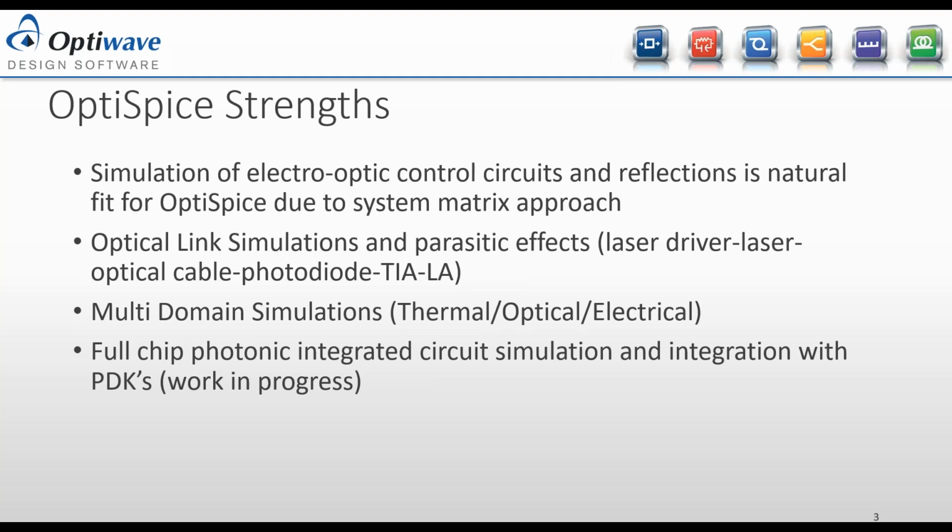One good example would be if you have a laser and near this laser you have a ring resonator, whose resonance is dependent on temperature. On top of that, you can have a system where you have a detector and a controller which changes the temperature of the ring resonator to change its resonance. So it can detect whether the ring resonator is on or off resonance and then change it, keep it there or change it based on the user request.